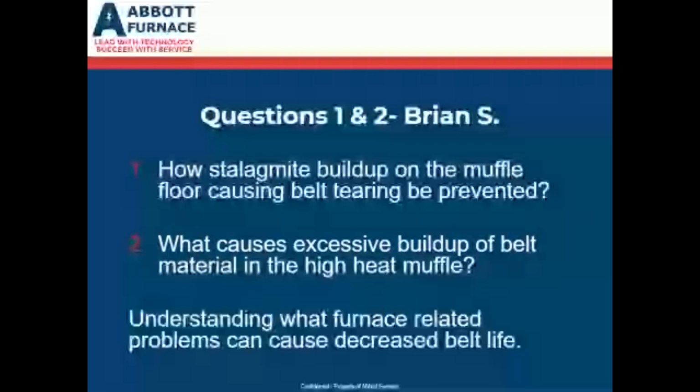And as that soot or carbon gets dragged back into the higher temperature zones of the furnace, it becomes stuck on the creases between the muffle sections and anywhere there's a little bit of a hump or anywhere that there's allowed to be buildup. And as that carbon builds up, it reduces in that higher temperature heat zone.